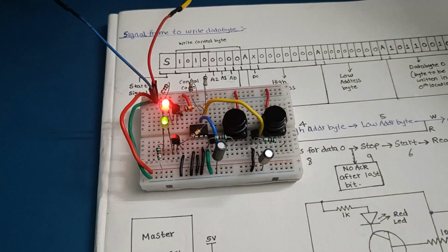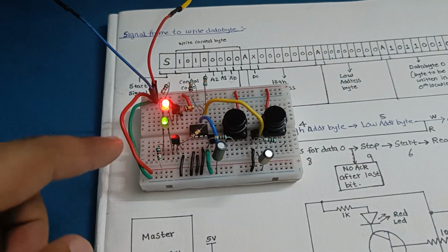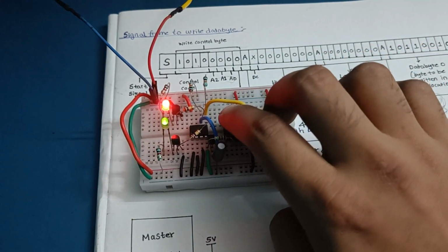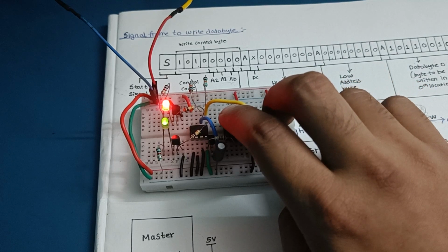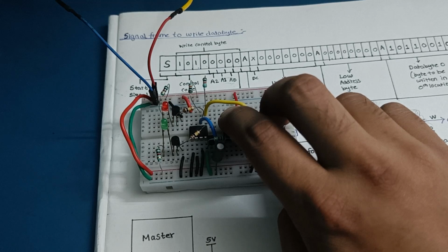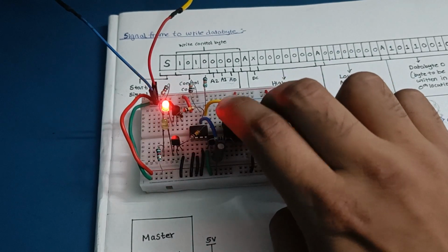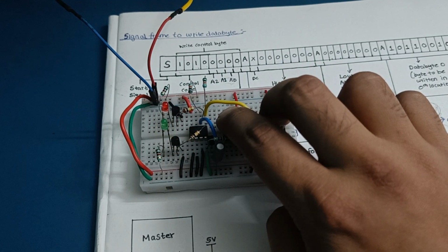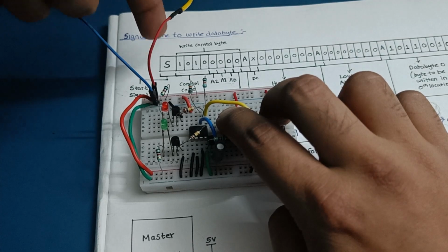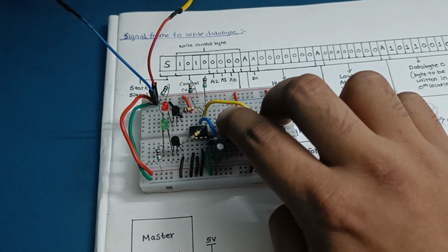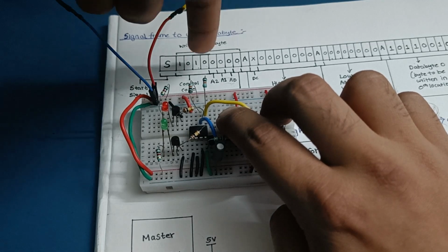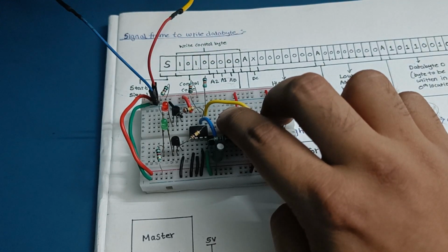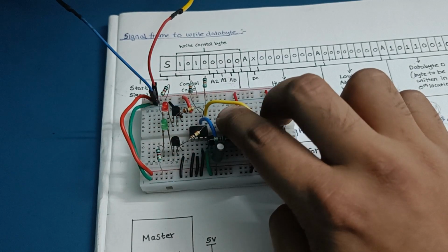So we'll power this on. Right now SDA and SCL are both high. Now let's write data to it. First we will initiate the start by pulling the SDA line low. Then we will send 1, 0, 1, 0. On the rising edge of the clock, the data is stored. So 1010 is the fixed control code that we have written. Now we have to write three zeros, which is the address A2, A1, A0. Okay, so 0, 0, 0.